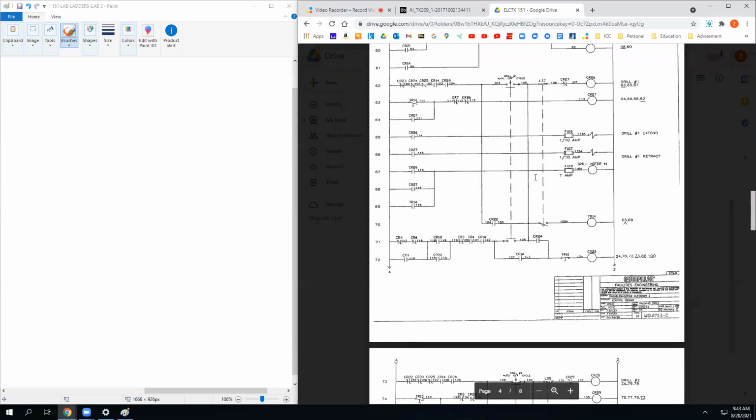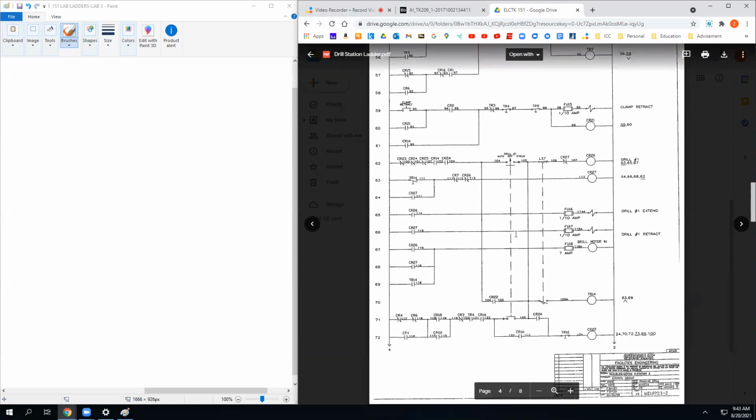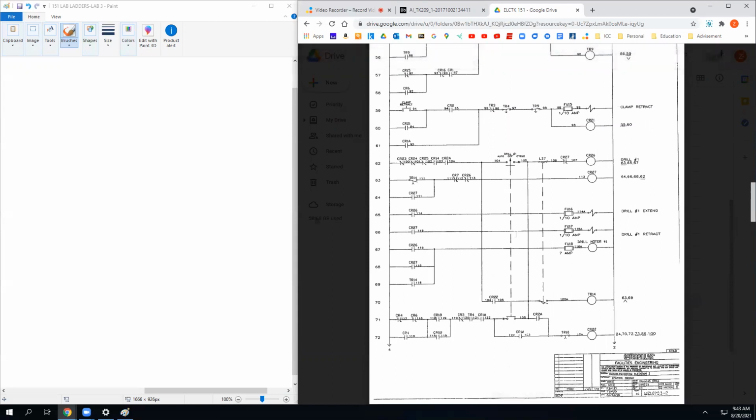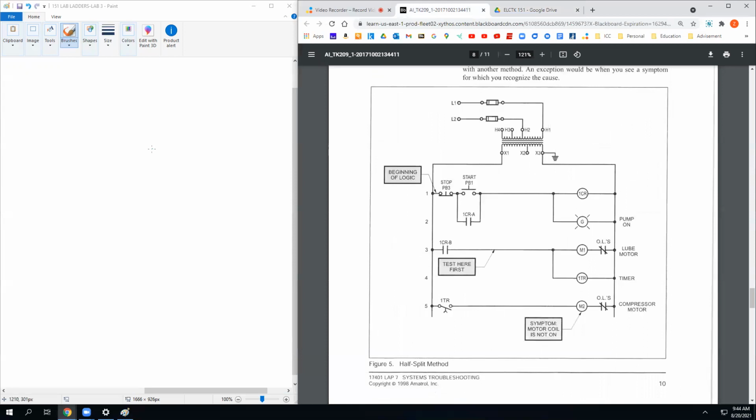So to go to the middle page here, the middle set of rungs, check a voltage somewhere in here, and then decide that the problem is either on the line side or the load side of that somewhere is just wrong. There are too many jumping-around places in that process. But here's where the half split method really comes in handy. I've used it a lot in lighting circuit troubleshooting. For instance, I'm going to draw a big old long circuit of lights here.